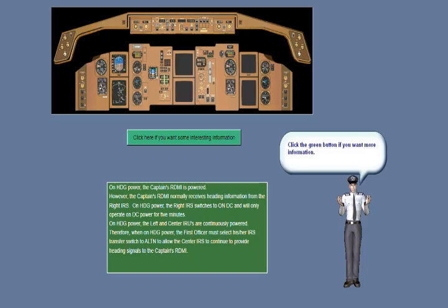A hydraulically driven generator, or HDG, provides a fourth generator electrical power source, albeit a much smaller generator than the engine or APU generators. The HDG is a non-time limited generator capable of operating essential systems for ETOPS operation.